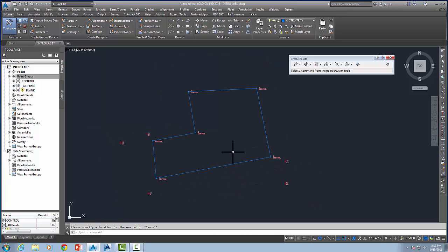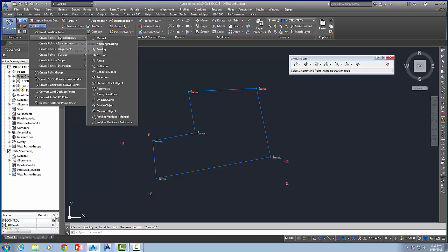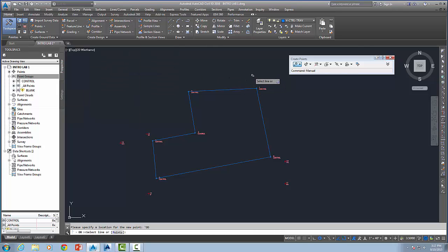What we're going to do now is establish point 8, which is out in the intersection of Pleasant Valley Road and US 127. So again, that is a turned angle, or let's see, yeah, that's a deflection. So you've got to look and be careful. Deflection is indicated by that little prolongation coming off here. So I'm going to select it near point 1. So it's backsighting 6, and you can see my prolonged line.